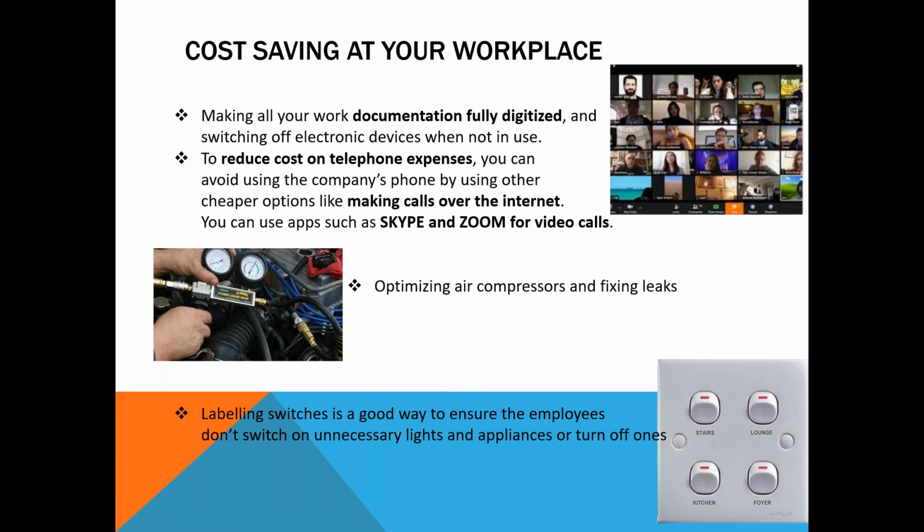So that was leakage. A leakage detection device is also available in the market, so you can find out where the leakage is and optimize. Out of 2 compressors, only 1 compressor is running, and that fellow is saving about 62,500 rupees a month. This is nothing but optimizing the air compressor and finding out the leakages.